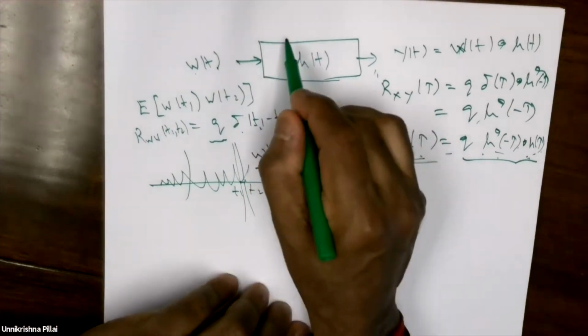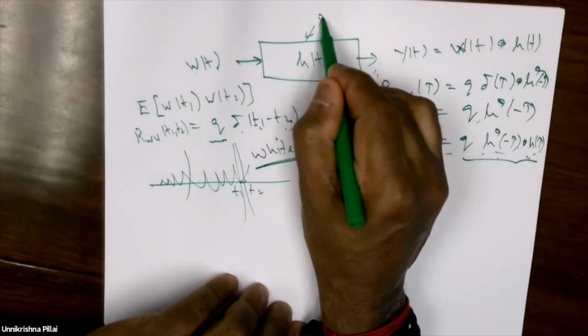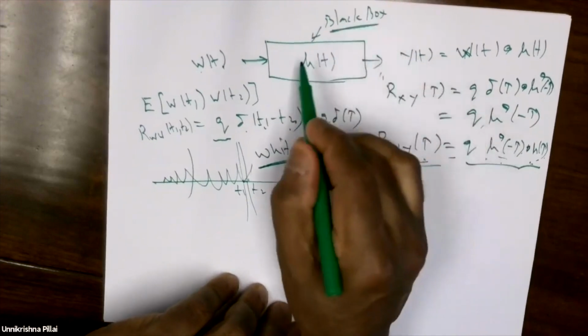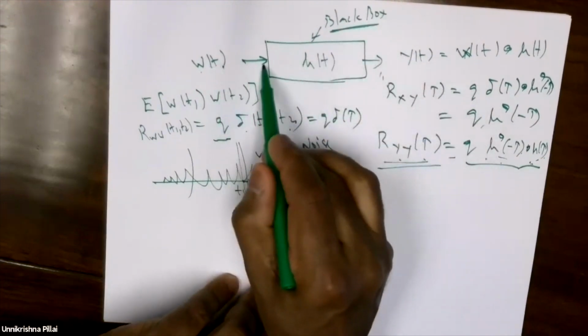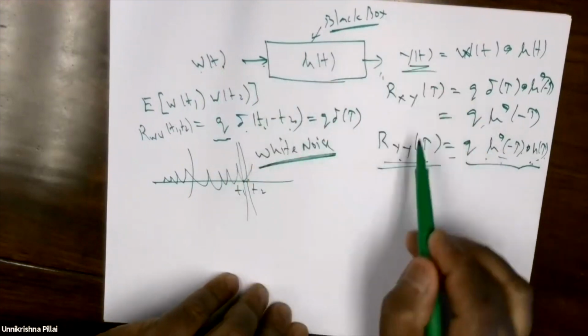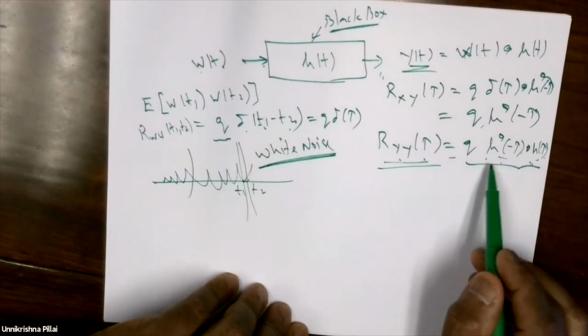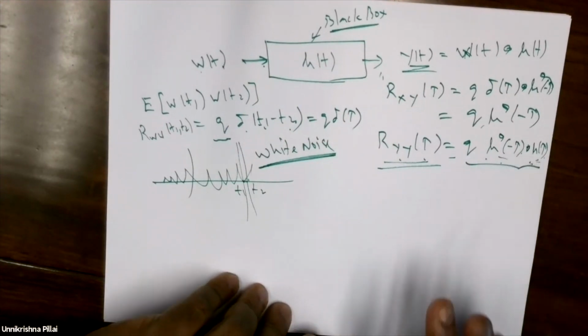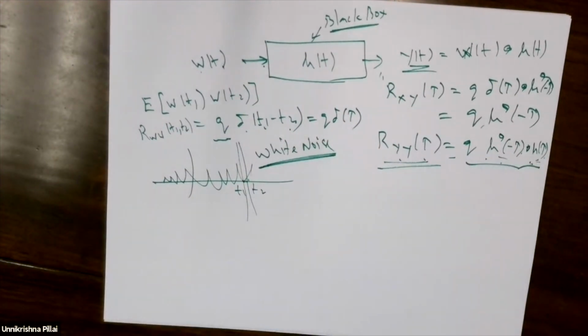If you have a black box and you want to study a linear system, you can excite it with white noise and look at the autocorrelation function of the output. From there you can find out the system poles and zeros, etc. This becomes clearer when we study the corresponding power spectrum. So this is just an application already of that.